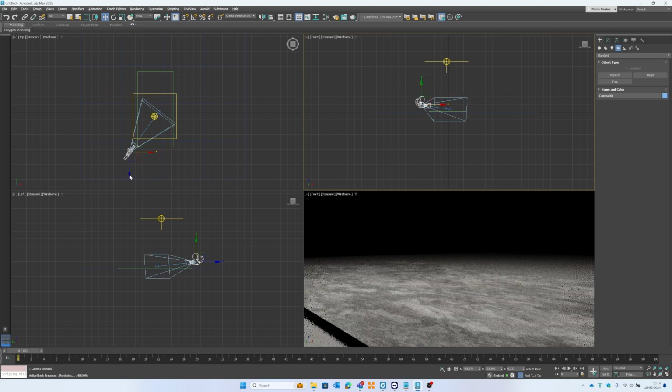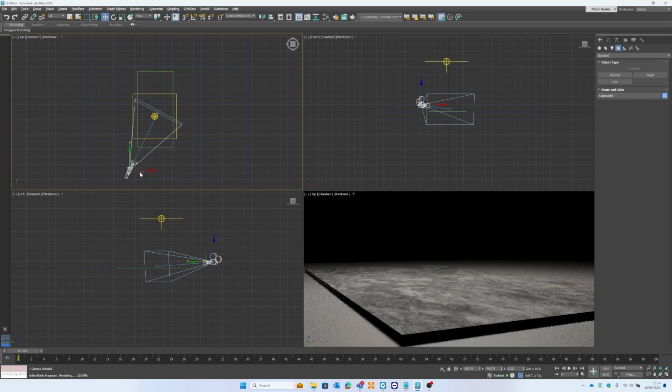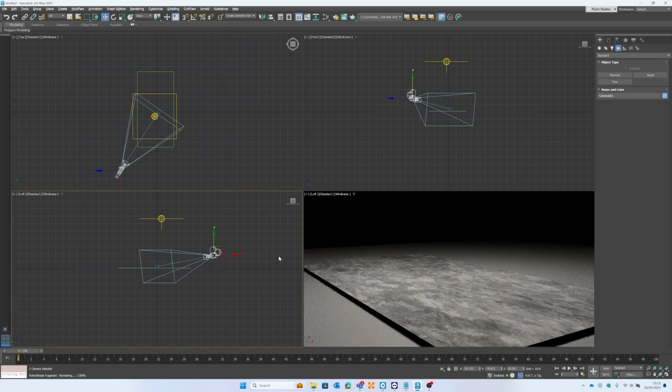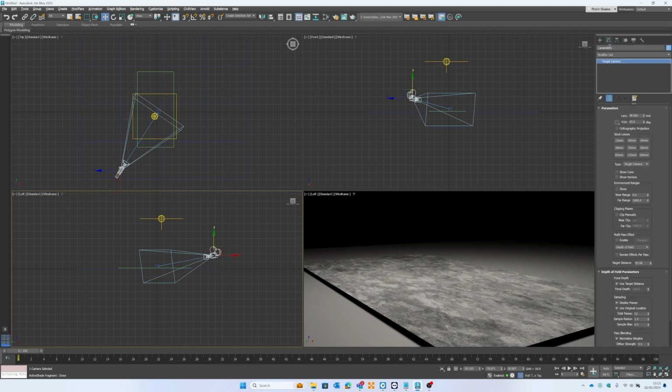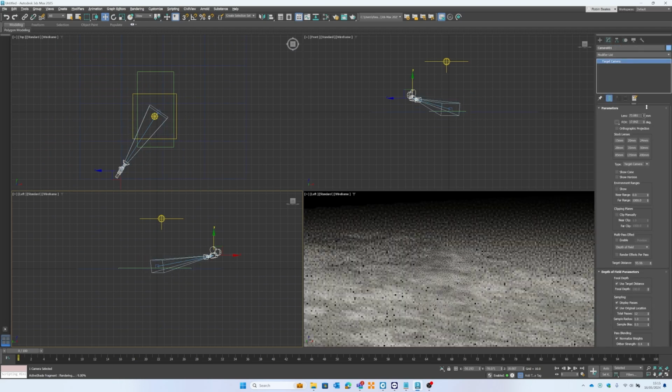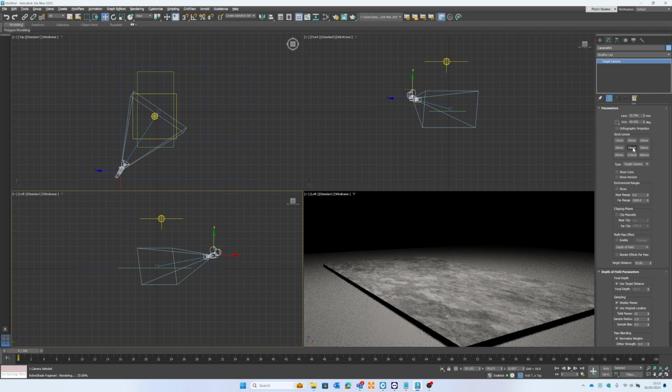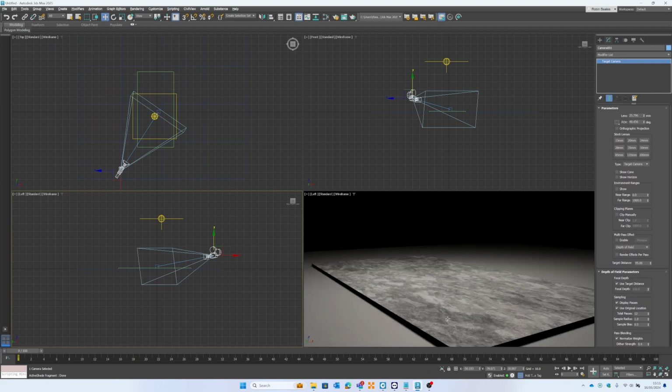I'm going to move the camera back a little bit, so in the Y and the X, so I can see more of the product. Maybe up a little bit more, so we're looking a little bit further down on the product. Something like that is looking pretty good. I also want to change the perspective. So I would grab the camera itself. I would go to its modify properties. And from here, you can change the size of the lens. That's going to give you a zoom. You can change the field of view to change your perspective. Again, you've got stock lenses. You can change all sorts of options on here, like what you would do on an actual physical camera. And again, get this so that it's looking the way that you want and reacting the way that you want.